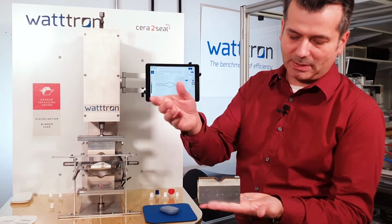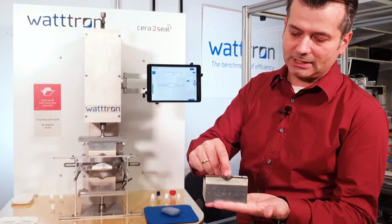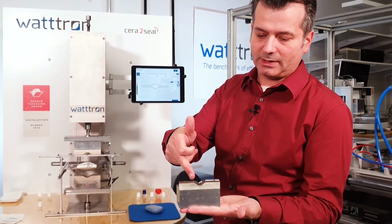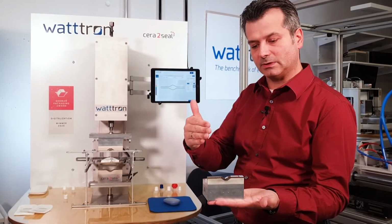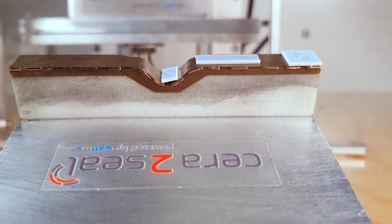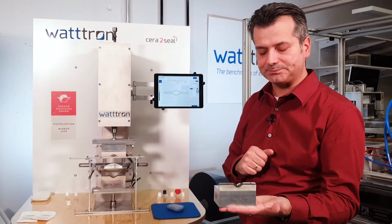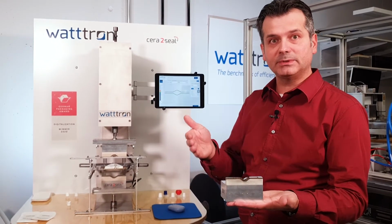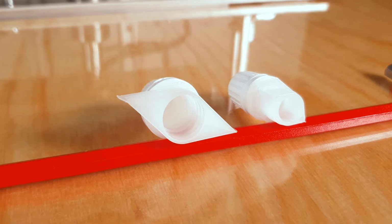So depending on the spout geometry, we choose different kinds of these heating elements, arrange them, for example, in that way, and put it all together in this geometry with a special metal alloy that is the closing, or the housing, for the ceramic heaters, which means a kind of mechanical safety for them. And with that alloy we are able to mill different surfaces, different geometries, depending on the final spout you have in your application.